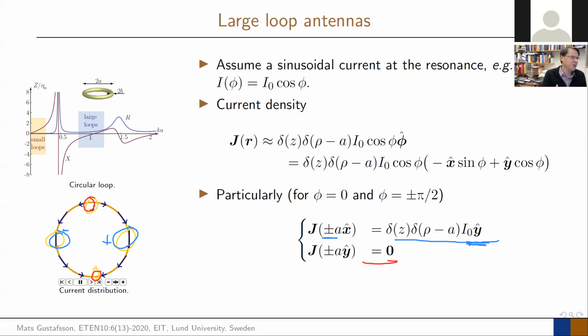So the radiation here will really be dominated by 2 dipoles, which are separated some distance here. So you have some distance d between them. That will give the dominant contribution of the radiation pattern. And again, as we said in the beginning, if you compare it with your patch, then you had like this and this. There is a difference with the patch antenna because those were magnetic currents, but the pattern will be the same, but polarization will be different. So this should look pretty much the same. And we only have to determine what is the distance between them when this is happening. And then we have an idea actually what the radiation pattern is.